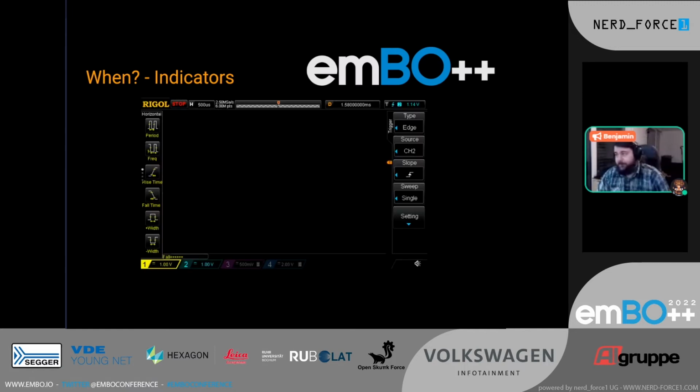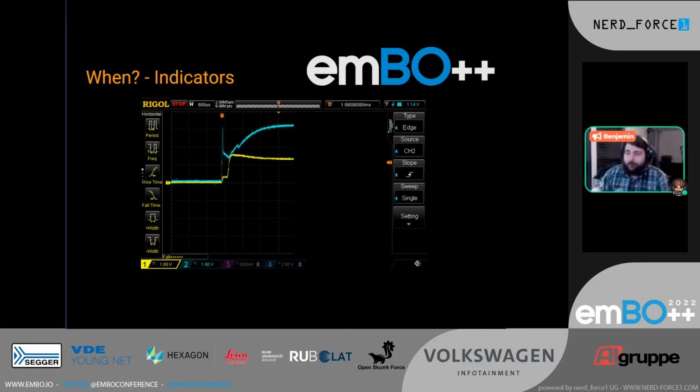So out comes the oscilloscope, and you will see in yellow the internal supply voltage, which I connected via the jumper wire. And you will see in blue the overall supply voltage connected to the development board. So let's turn on the power. And as you can see from zero, the supply voltage spikes. And then once the internal chip starts charging its components, once it starts powering up, there's a drop, because I think I'm drawing too much current for this GPIO pin I'm doing this from, but well, it hasn't burned up yet, so it's fine.